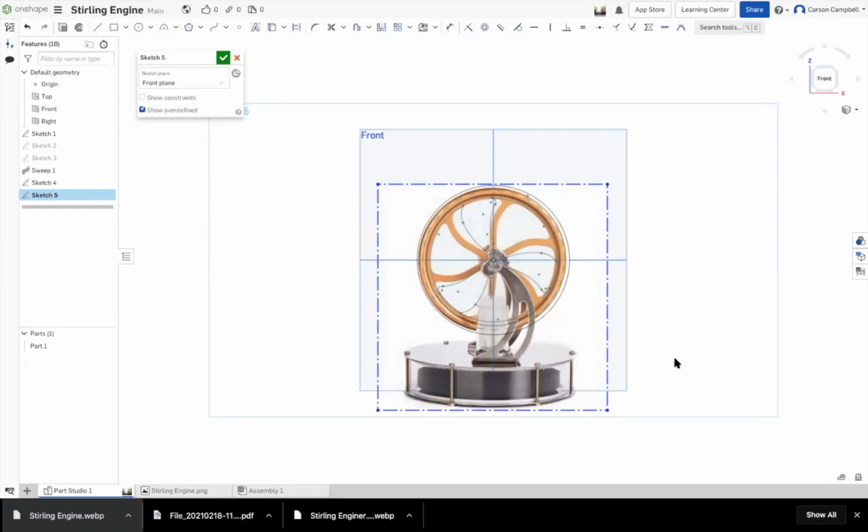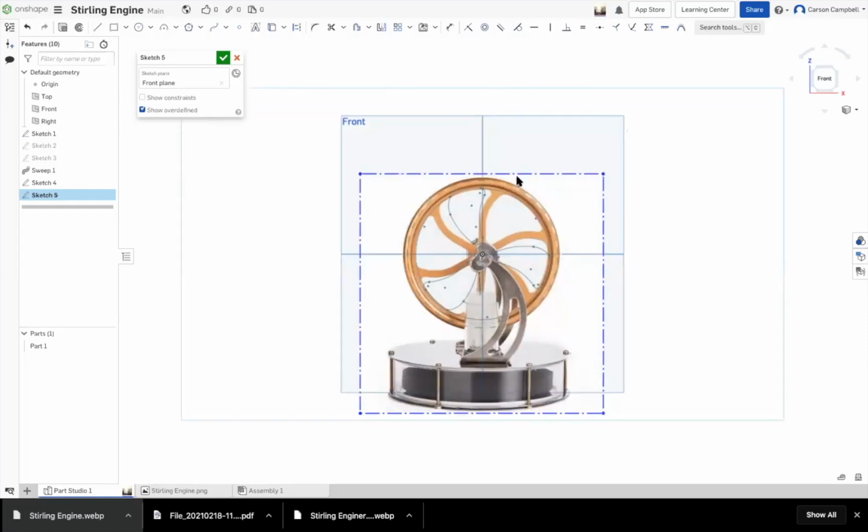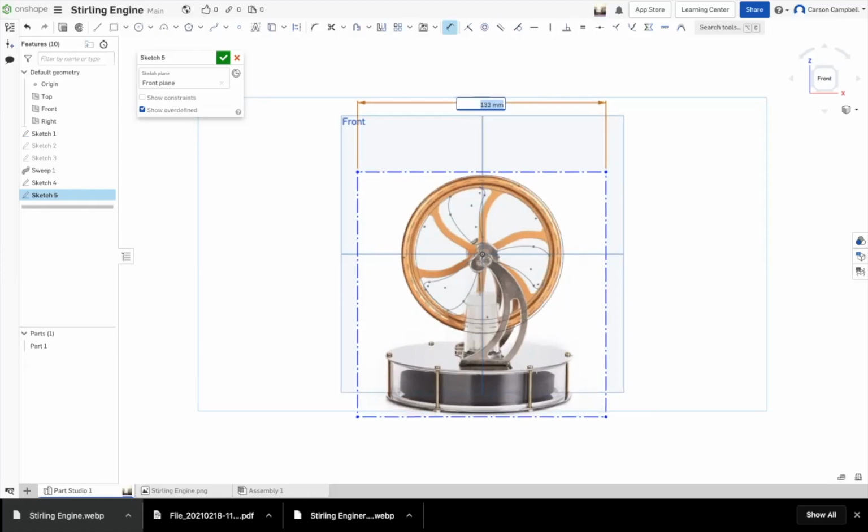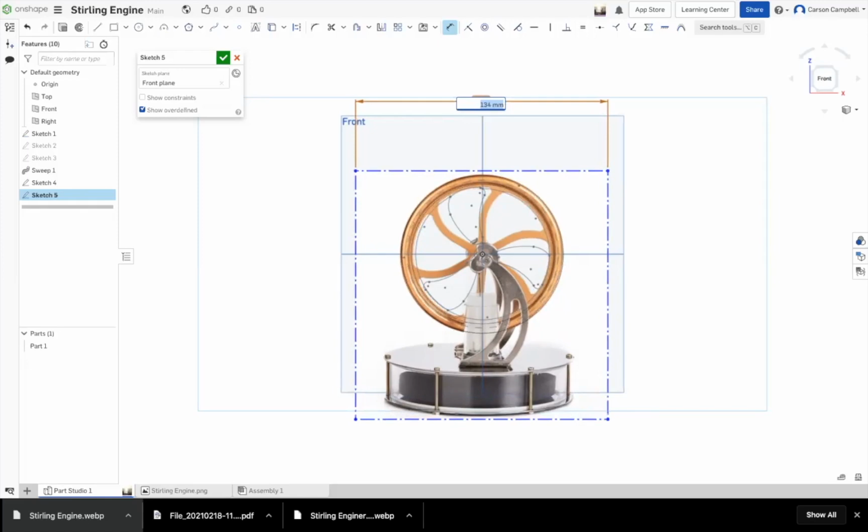Now, what I would do is put a dimension on the top dash line, D, place it, yeah, and change it to 130, 131. So double click on one, nope, escape out of that. The aspect ratio is what you're controlling there. It will work properly without a second dimension, only one. So double click that. Hit the up arrow key on your keyboard and keep going until it's about as good as it's going to get. That's probably it, huh?